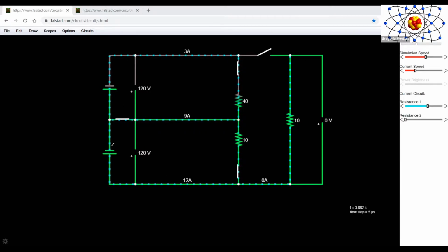And these 12 amps are coming from here, okay? And what's happening is that you have your 12 amps on this load minus the 3 amps on this load. So the amount of imbalanced load is going to be equal to your 9 amps right on this load here.